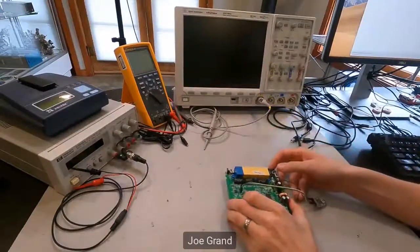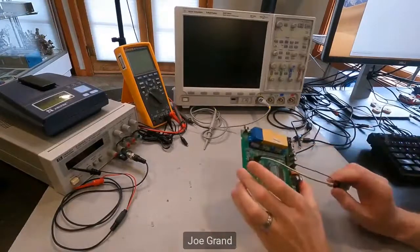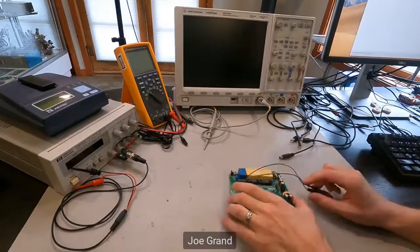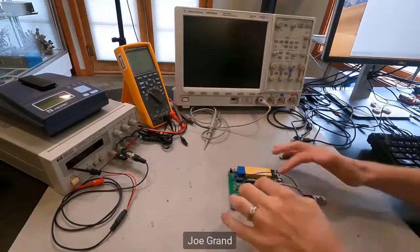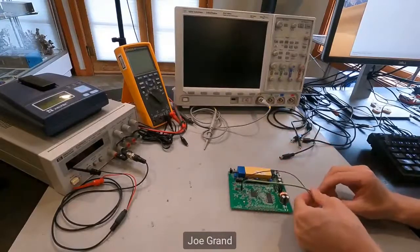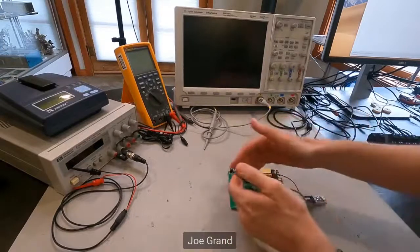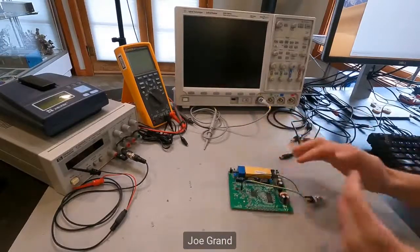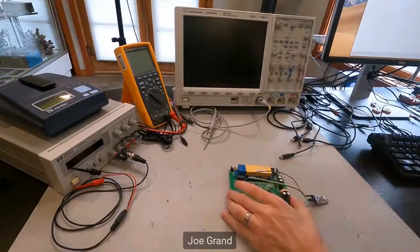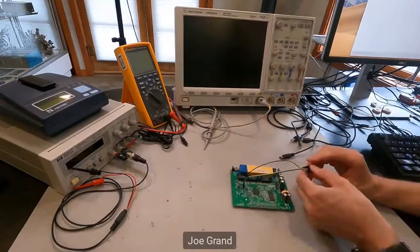Now, the reason I'm using these is because they're so common, and if you want to get into hardware hacking, you can go to Goodwill, you go to a surplus store, you can buy these things for $5, $20 or whatever, all day long, and you can hack on them and get more. And it's a great platform because things are exposed. There's different types of memory devices and stuff to play around with. And generally, they're all running some sort of Linux. So you'll have a UART interface. You'll probably have a JTAG debug interface that you can hack on. And a lot of the community has been working on different types of access points and routers to reprogram them with open source hardware and all sorts of other stuff. So really kind of cool.